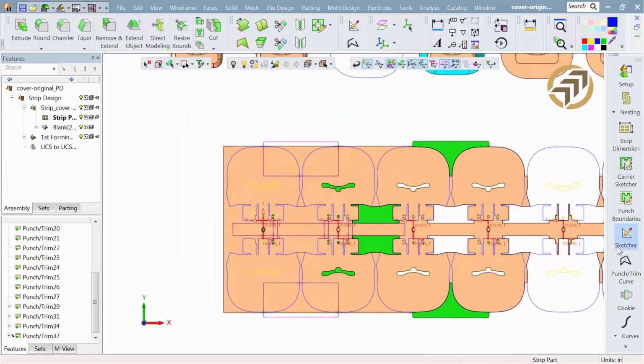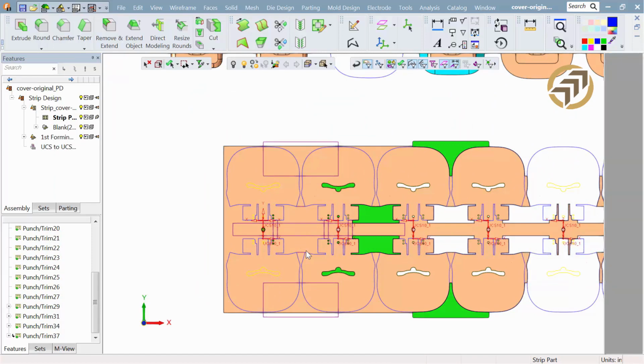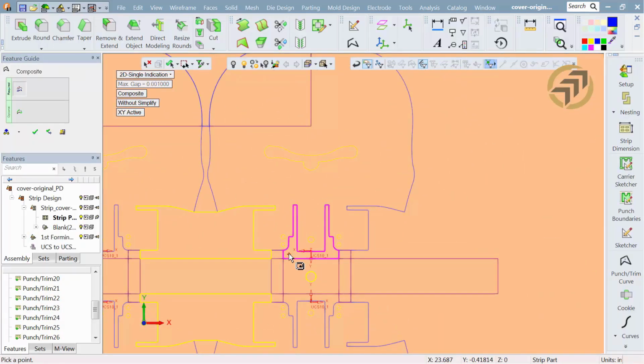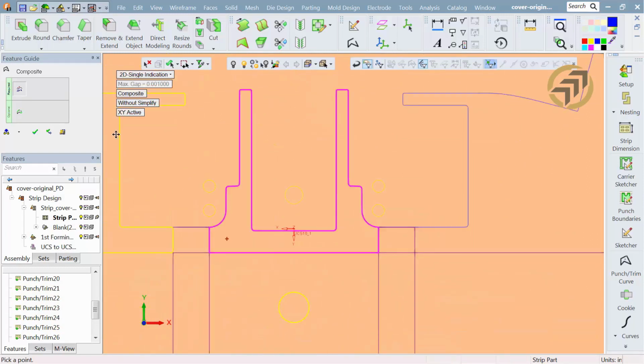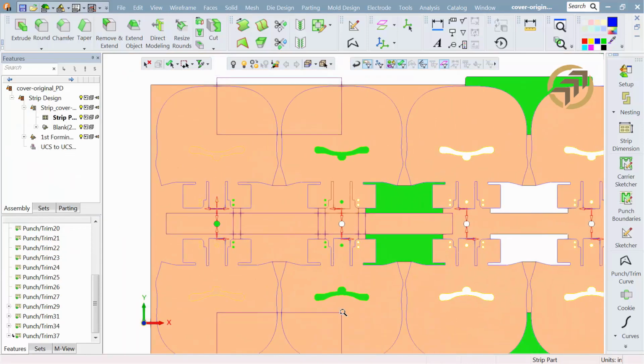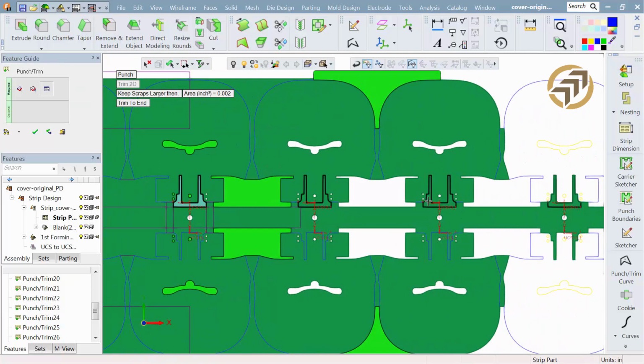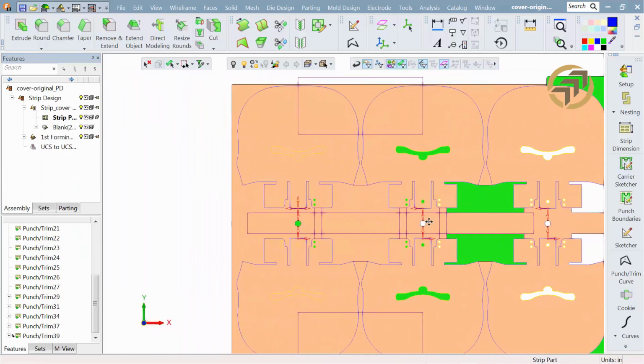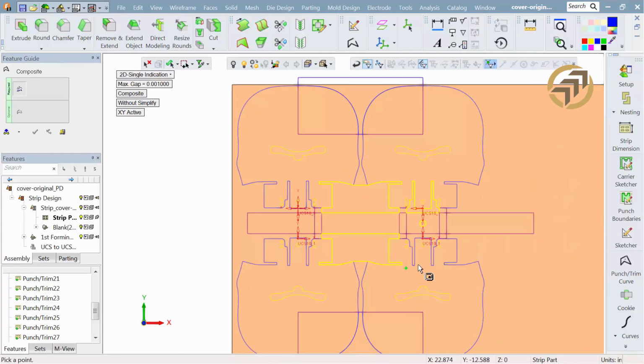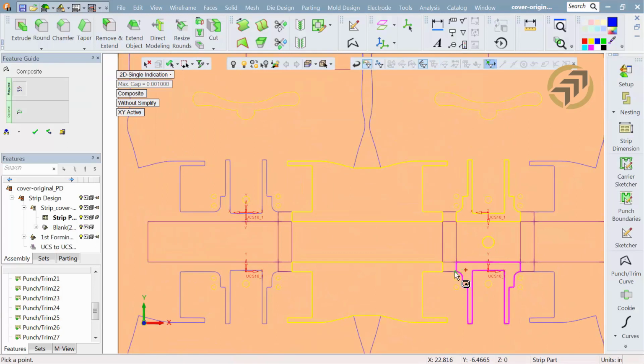We need to get the area inside. Alright, right there. Again, I want to put radiuses on that. So pick the particular corners where we need those radiuses. Alright, now where do we want that to go? Let's find an area where it's got enough distance. That looks good. Again, if designing you find that they're too close together, we can go back and we can relocate where that punch occurs.